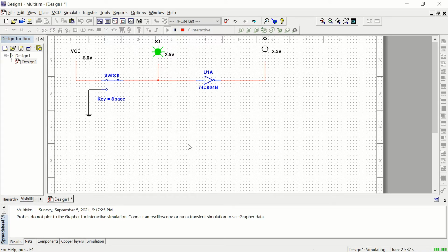And so the function of that particular gate there is it changes the value. And so I can hit my space bar a couple times, and you notice that when the first one's low, the second one's high, first one's high, second one is low. And so what you need to do on your worksheet is fill in the 0 and the 1 for the input. So the input could either be 0 low or 1 high, and then the output is the opposite of whatever the input is. Logically speaking, this is called a negation in mathematics. In engineering, it's called an inverter.